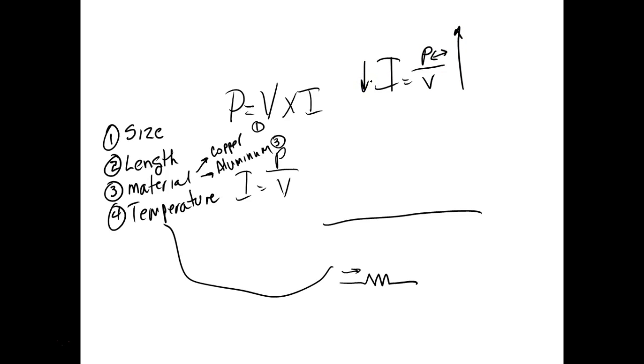So what do Alabama Power and TVA do when they transmit their power? They step it up to a really high voltage, right? Because what happens? They're not trying to sell current. They're not trying to sell voltage. They're trying to sell power. So the higher the voltage they transmit that power at, the lower the current, which means now instead of using copper, I can go to aluminum for my high tension lines, right? But you're talking 200,000 or 300,000 volts over there.